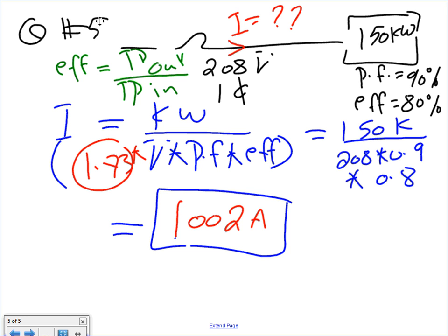If you multiply 1.73 times I times V, you basically multiply the whole quantity by it. For all practical reasons, everything here will be multiplied by 1.73. What it means is you modified only the voltage because it's three-phase, but it affects everything.